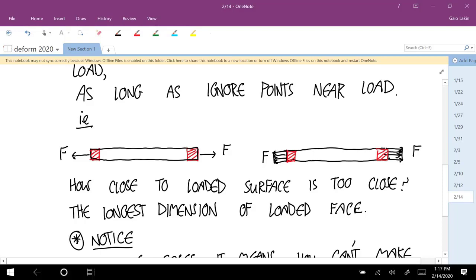But what we're going to do gives us a way to do a quick hand calculation that should match up with finite elements. So in a way, you can troubleshoot your finite element results with the kind of calculations we're doing. And then there are other cases where, if most of the steel in your structure is made up by the bulk of the beam, you don't want to worry too much about what's happening at the end. Just load up steel at the ends, put big gusset plates or whatever like they do on a bridge. If you ever look at the truss that makes up a bridge, they have thick steel plates that connect the beams together. You don't have to worry about what's happening there. All you have to worry about is whether these are going to buckle or whatever.